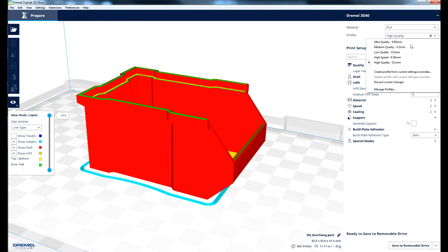This is a general term that covers two main characteristics, layer height and print speed. Both are directly related to each other. This can be best seen by the estimated print time when slicing your part. Low quality settings are always faster compared to high quality settings. The difference here is how many layers your model is sliced into.